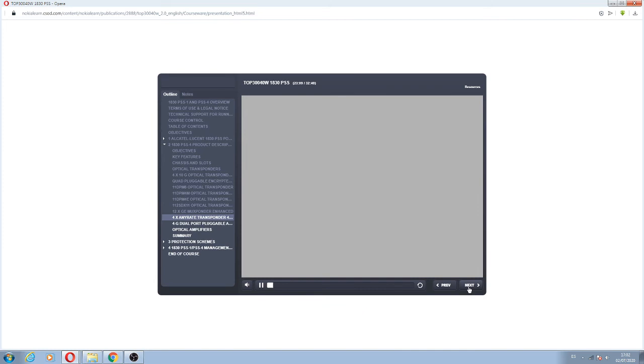The 4DPA4 board is a half-height, single-slot wide card. It has 8 SFP ports that support 4 any-rate SFP client interfaces, 2 SFP line ports, and 2 EVOA ports. This card supports 1+1 electrical SNCP option. The card supports fault processing and signal monitoring. It supports wavelength tracker with EVOA SFPs on the 2 DWDM line ports.